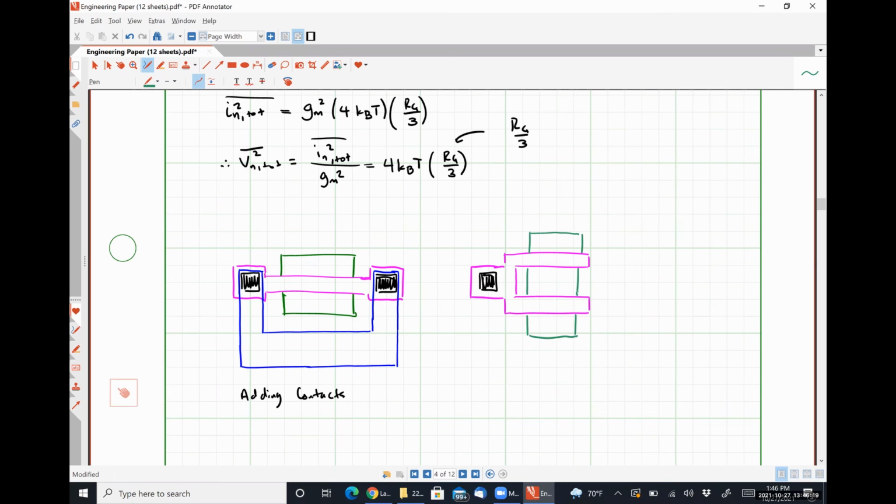So in this one on the left, obviously the poly is our gate. Let's call this one on top our drain, and this one on here our source. And we're literally just lowering the resistance because we're forcing that polysilicon to have another parallel path that's effectively nothing connected to it. And so we cut down that overall resistance by a factor of 2, which cuts down the noise by a factor of 4 because it's always based on the resistance squared.